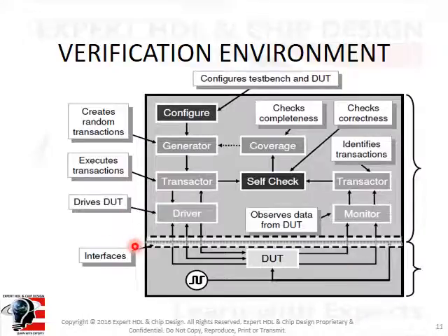The verification environment is a platform for testing a design with various resources like a test bench generator, which drives the test bench based on various inputs and scenarios; a driver, which drives the test inputs; a monitor, which checks the outputs; a comparator, which compares actual versus expected output; and finally a scoreboard, which keeps score of the number of tests failed and passed. Most of the components are designed to be reused across designs under test. A verification environment helps automate most of the verification process.